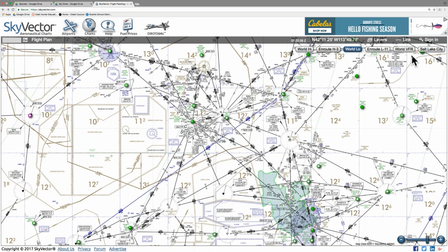If it has an ILS approach, 99.999% of the time, I can't think of any other time this would be wrong, your ILS is going to give you the lowest minimums. So that's where we want you to look first: see if it has an ILS approach. Okay. I had all the category 1 half mile and 2400 RVR, but okay. Just checking.